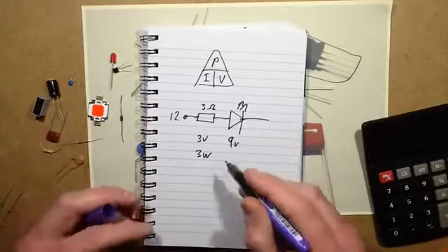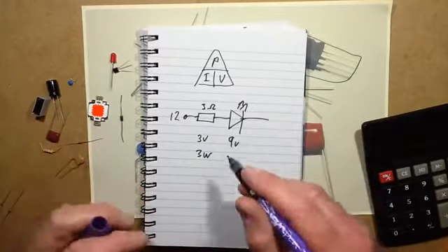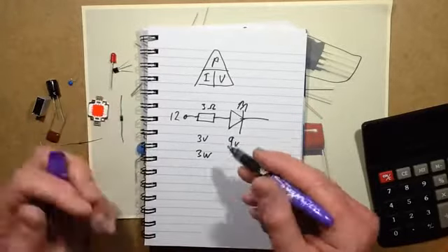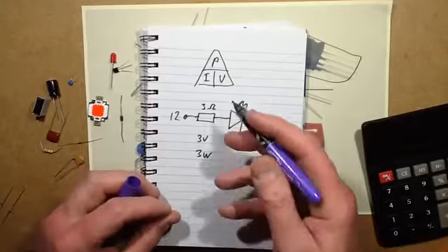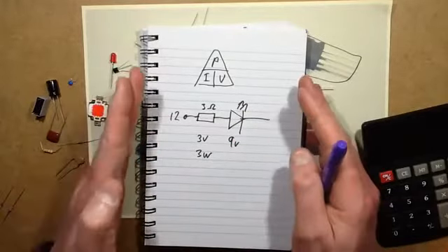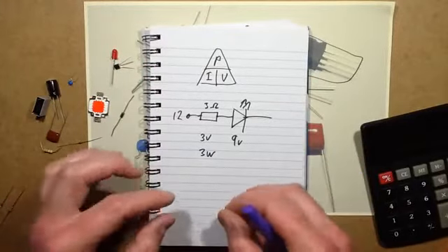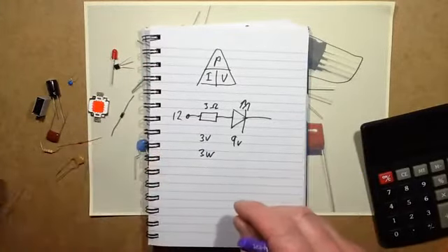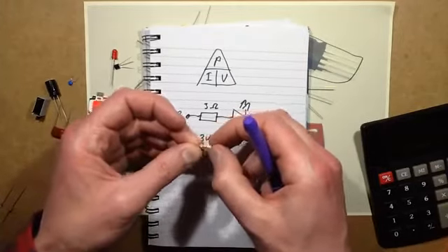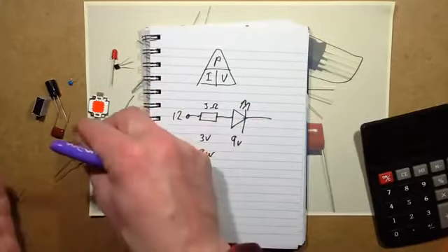But we'd actually be better choosing a higher power resistor. And it's not a terribly efficient way to drive the LEDs, but it works. It's very, very simple. I'd probably choose a 5 watt resistor because you want it to stay cool. You often see resistors that have just been pushed too far on printed circuit boards. They've been designed and they've said, I need a 1 watt resistor. They use a 1 watt resistor, and instead of a nice colour code, it's basically the whole thing is just brown, and the circuit board shows heat round it as well. So it's good to get rid of that heat.